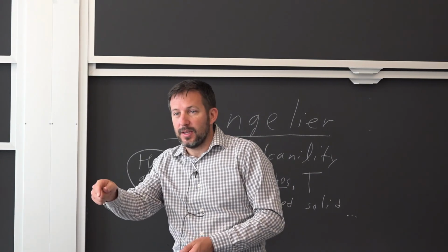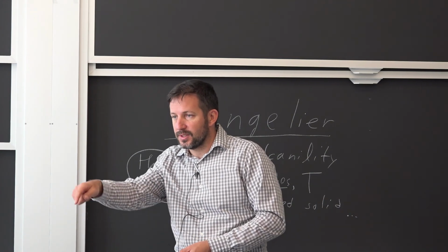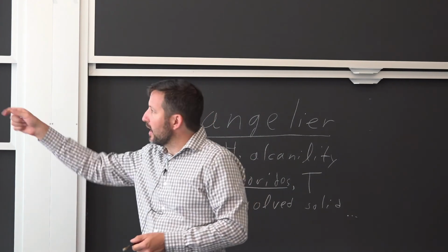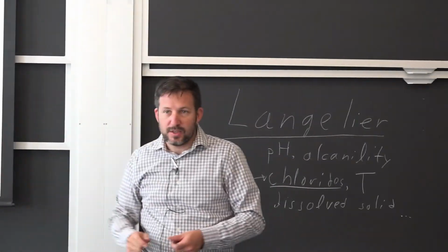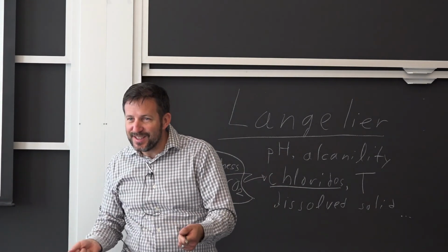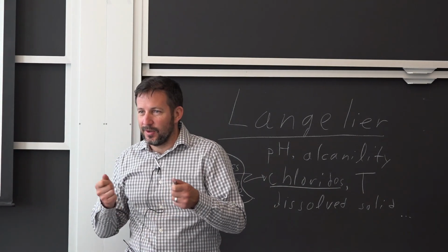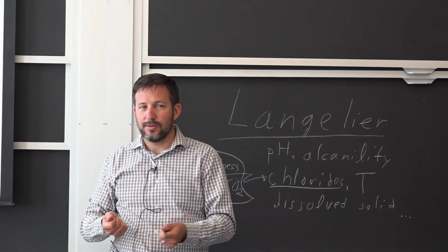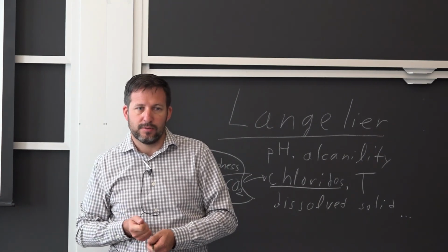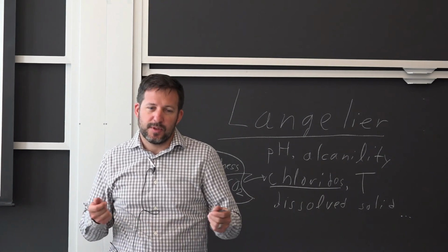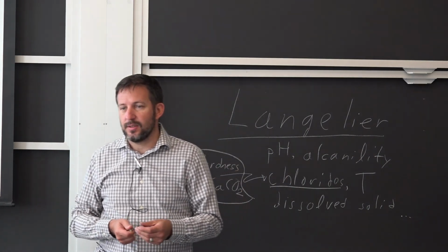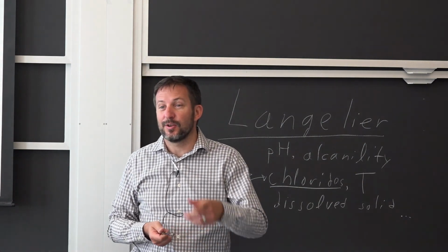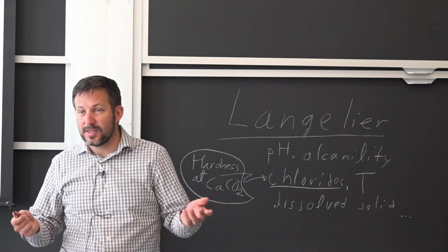Because the environment is the soil and the moisture, that's the path for the electrolyte, and you made that electrical connection. The reason for having that access hole is you can go in there with a voltmeter and see if everything is working. Am I applying the right voltage still today? No, it went down, so my anode's gone. I need to put more anodes into the ground, or sometimes you could say, well, it's kind of dry, so it's very high resistance, so you actually didn't really need the anodes for this particular case. So now you go on the day that it's after a big rain to see what's going on.